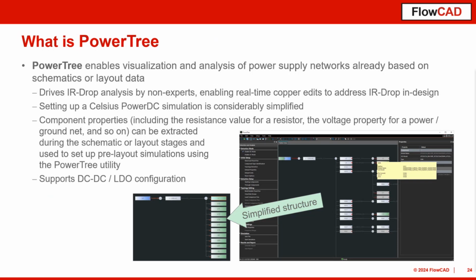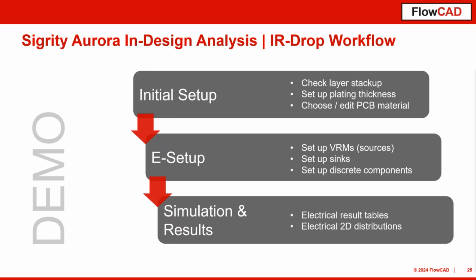And what we can also do right now is assign the currents to the things that are necessary for the simulation. Once this is done, you can save this file, and you can also use it for the Cadence Sigrity tools, for example Power DC, Celsius Thermal Solver or OptimizationPI. So this is a very, very useful way to define your power distribution networks.